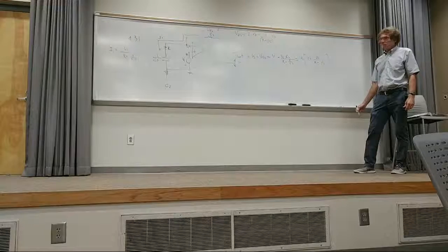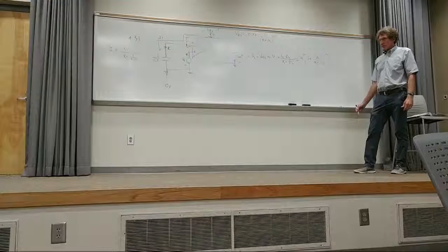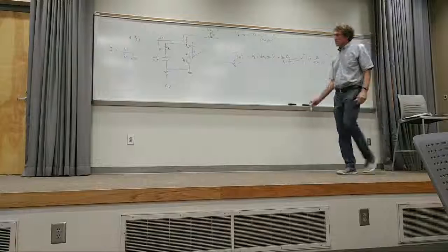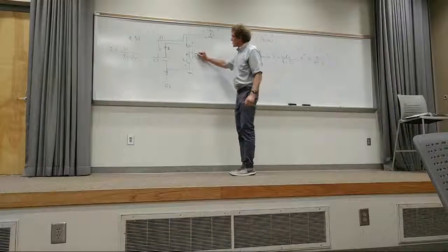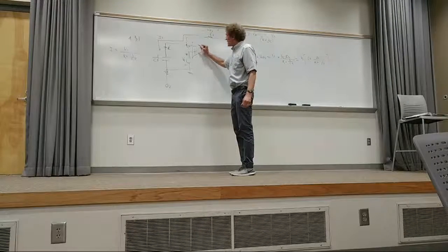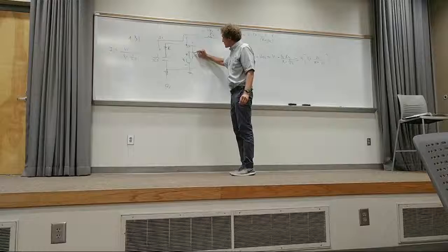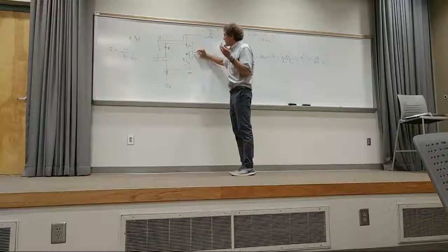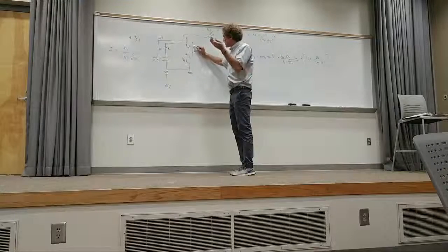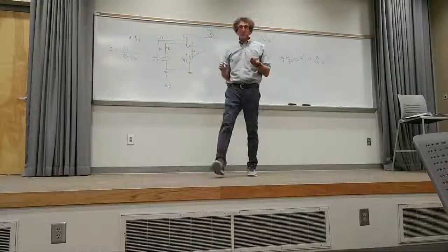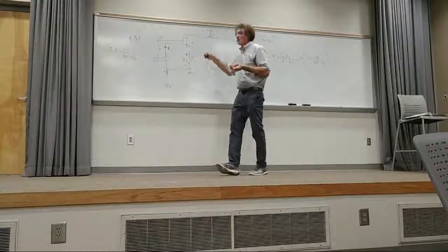Yes, sir. So, you said that there's no voltage difference between here and here. Okay. That means the voltage here must be the same as the voltage here. Gotcha. That's all it means. This voltage, in the book, it will have V sub plus equals V sub minus. All right? 1 volt here, 1 volt here, period.